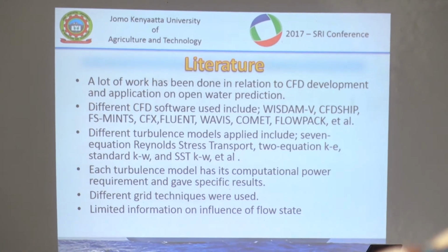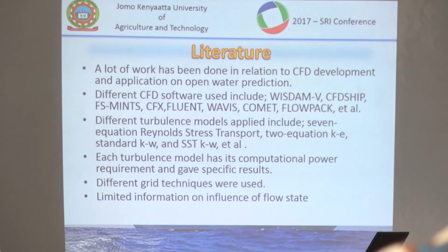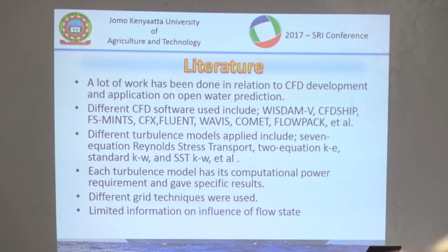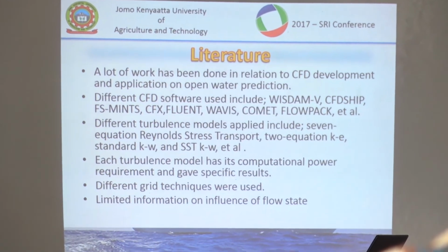Now the part which is moving is usually attached to the model, and several tests can be done in a tiny tank. For example, you can test seakeeping, whereby it is meant to move in waves. There are artificial waves in a tiny tank, so it can be moving as you generate waves, so that you can see how it reacts to the waves. Because ship resistance is usually in 3 parts. There's the pressure, because there's a pressure difference in the water height. And then there's the drag, because the water is sticking on the hull.